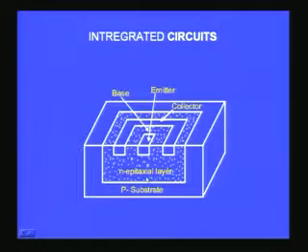where we have shown actually a transistor. You have a basic p substrate into which you generate an n type epitaxial layer, and then you have a collector and you have an emitter, and whatever is in between, the n type epitaxial layer, forms the base, and so you have a PNP transistor on the same surface. So one is the emitter, the other is the base, and the other is a collector. So you can form them, and you can take leads from here, metal leads from these, and then they can be connected to other parts of the circuit. So this forms an integrated transistor.